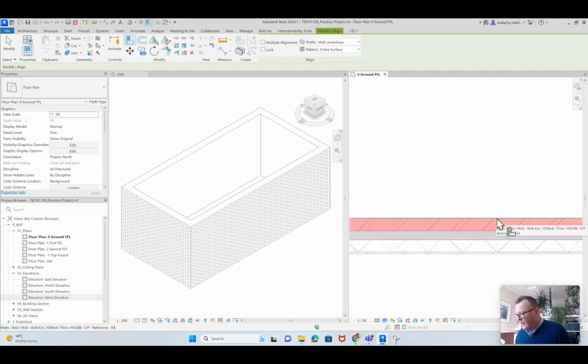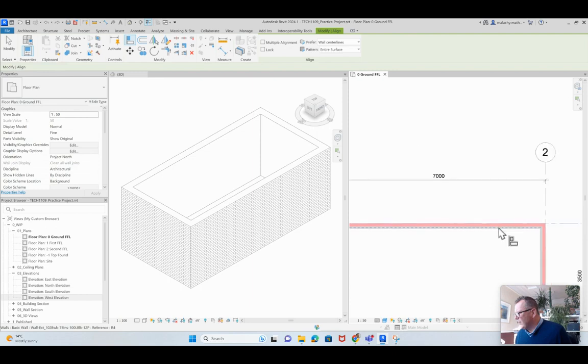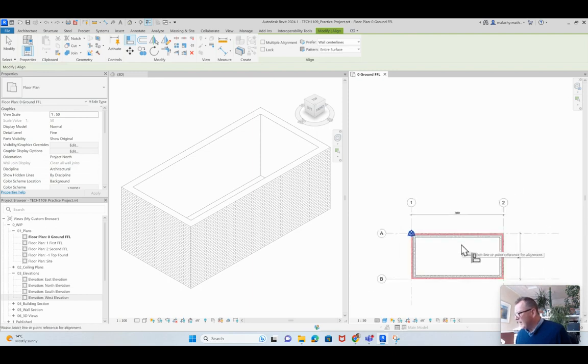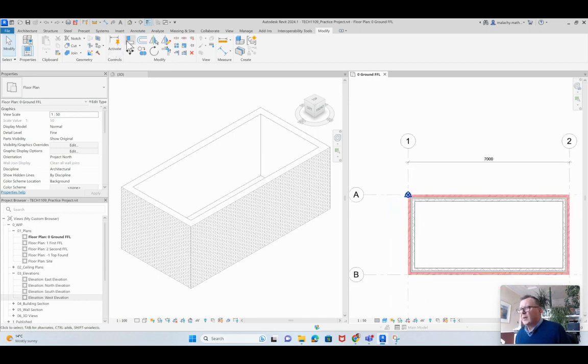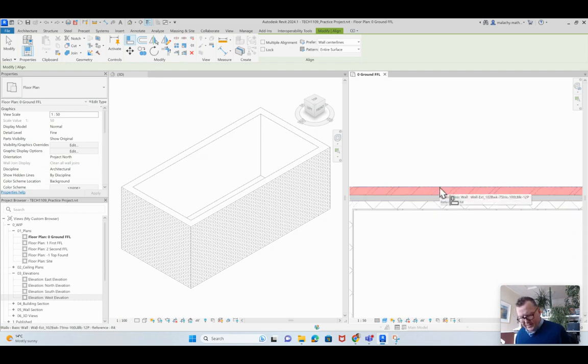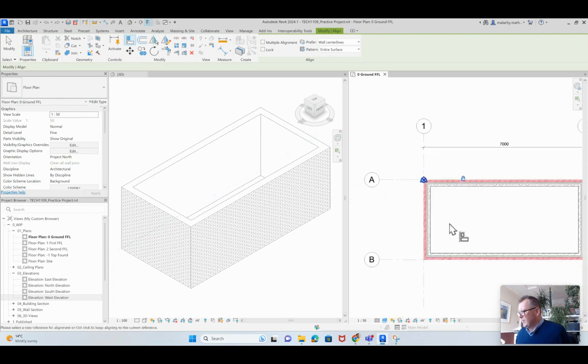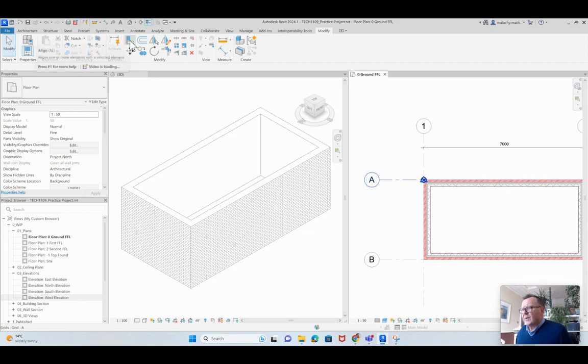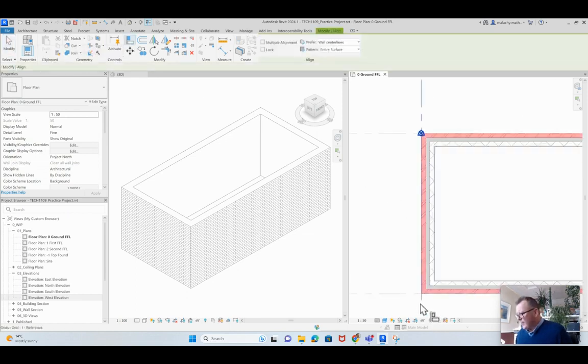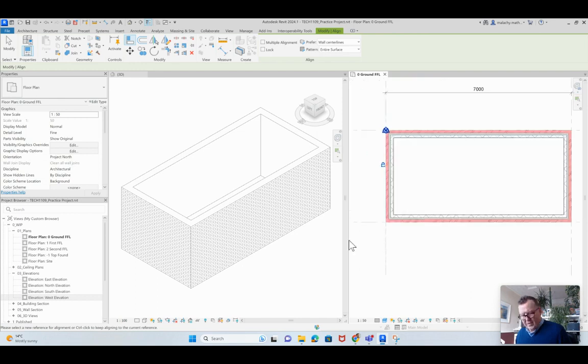So I got a 0 in here. I could use my tab to that one, and it's not coming up. Okay, let's try that one more time. Okay, to this align the outside. So tab. Now there it is. There's my little lock put in place. So I'll do that again for you here. And listen to what I say. So I hit the align tab and I go to this grid, align this edge, and I have to tab to get the edge. Then I can lock it. All right. And we'll do that one more time here.